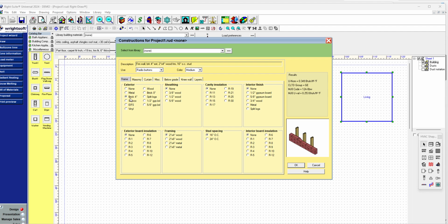Sure, it's kind of like stone, right? Or stucco, either way. Either one is fine. For sure we have sheathing. It's more of a newer home. It looks like it's going to be more of a luxury style home. So they probably have some pretty good insulation, like R13. Okay, interior finish for sure. There's going to be sheetrock on the inside. It's probably 2x6 construction. Okay.